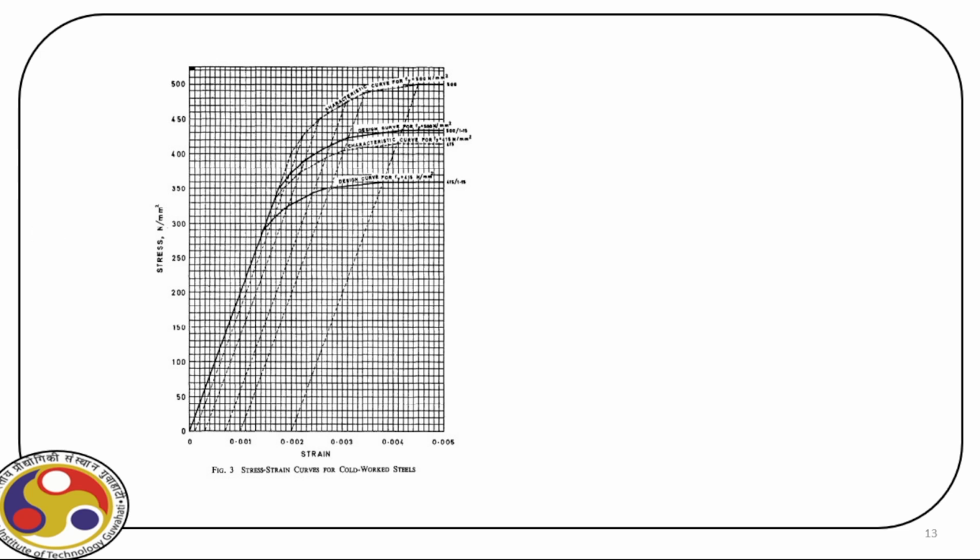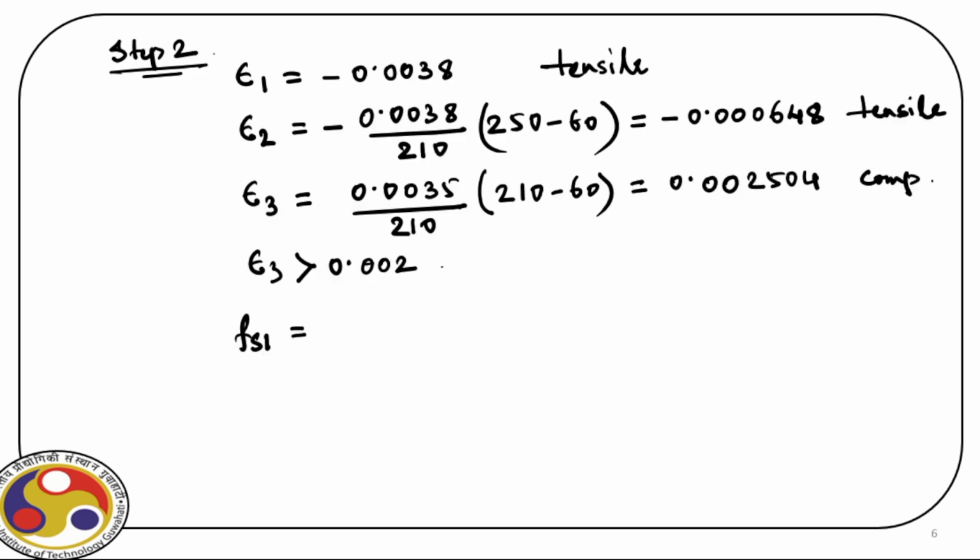And depending upon yielding, we need to see whether we are in the linear part or we have to read the stress beyond the yielding point, right? So for the first one, again, we have minus fy divided by 1.15, that is 0.87 fy if you recall. So this is 361 Newton per millimeter square.